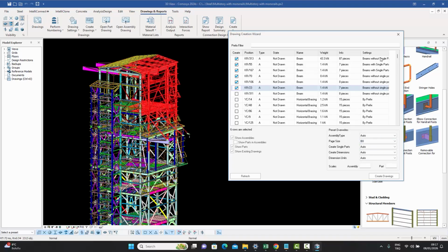So I have a certain page size mentioned in these, but my page size preferences keep changing from project to project. So I don't want to keep adding to those presets every single time for every different page size. I've got the generals because there are hundreds of settings in there, but the page size one is the one which keeps changing. So I can, at the last minute, just override that. So whatever you find in these presets, just override that page size by this one.